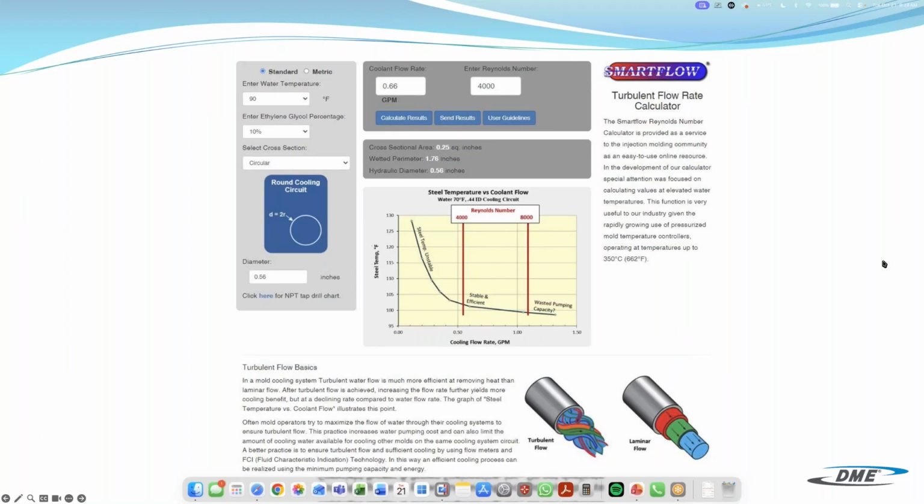Okay. Let's see, a follow-up for this one is, can you incorporate this with an existing system? Yeah, I mean, if you have a tool already in process, and let's just say you just have a manifold and you're just running the lines to the tool, yes, you can use quick connects and jump in. We always suggest take a quick connect, put a flow meter in there, and go from circuit to circuit to circuit and just see what you actually have. And that at least will give you the vision and give you the understanding of currently what you are running at.